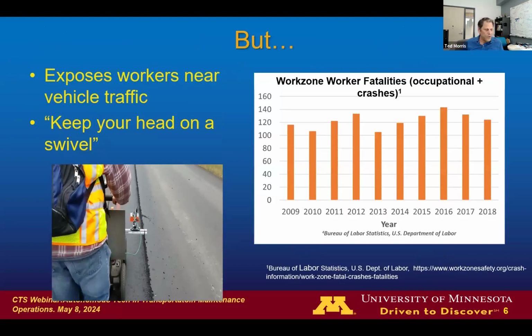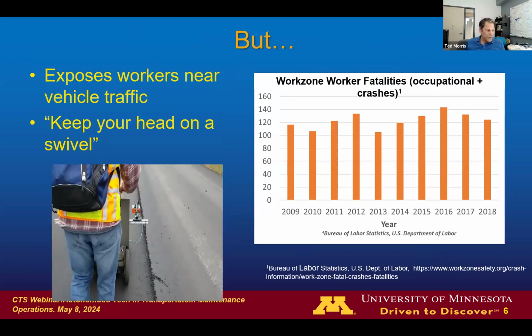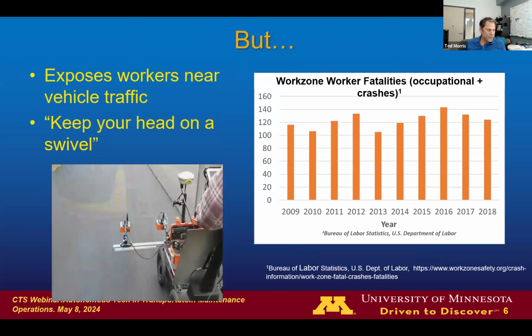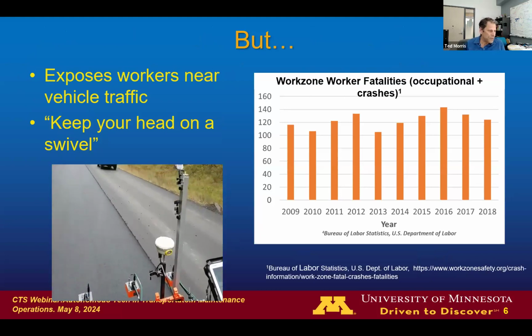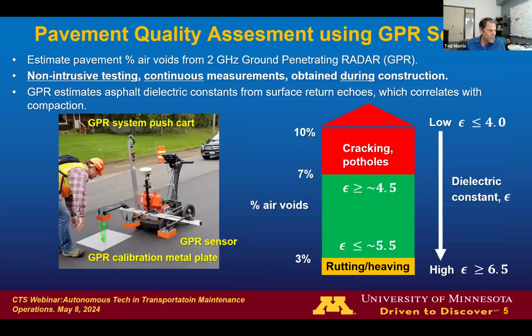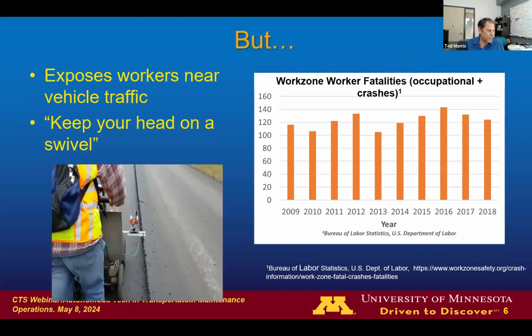by continually going over the roadway by just simply passing this dielectric sensor over the roadway. And one really important piece of information, I should just mention this, is that it can be used on fresh pavement. So this is before you can be driving heavier vehicles and such on it to do any kind of similar inference or measurements. So that's another reason it's becoming a popular method.